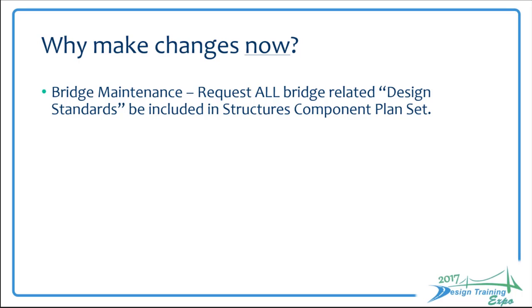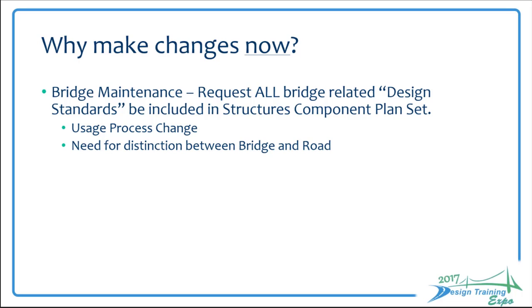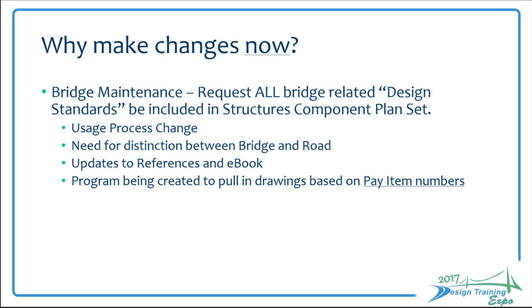Well, for several years, the Bridge Maintenance Office has been requesting that all bridge-related design standards be included in the structure's component plan set. This is due to the nature of the bridge design life lasting anywhere from 75 to 100 years, and the need for maintenance to be absolutely sure of what standards were used in the construction of those bridges. If we did this, our standard plans usage process would have to change. We also would have to distinguish between bridge and road, and also updates to references in the ebooks would have to occur. There's also a program being created to pull drawings based on pay item numbers from the standard plans into the plan set.